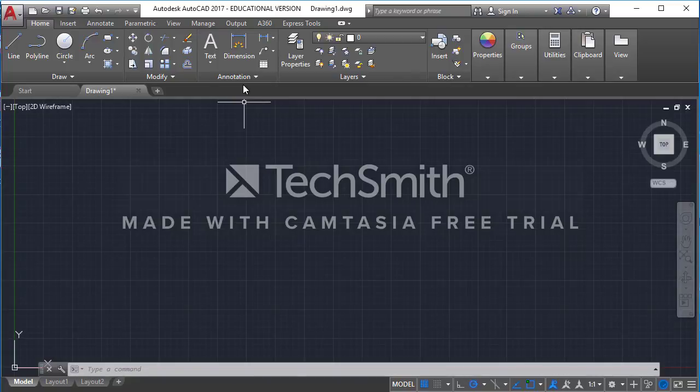Well, when you work in AutoCAD, you're going to work in full scale. You're going to draw things at the actual size that they are in real life. So if you're drawing a 24-foot long wall, you're going to draw a 24-foot line. You're drawing everything at the real size scale that you're working with.